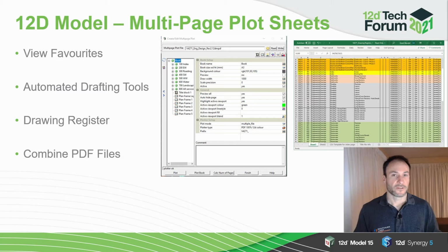So how do we bring all this together onto a plan face, and what council's going to see, what the contractor's going to see? It's all got to do with your plotting. So without having to take it out to CAD, we're plotting from the multi-page plot sheets using view favorites. If you don't already use favorites, whether you're plotting or not plotting from 12D, I recommend checking them out. They're super handy.